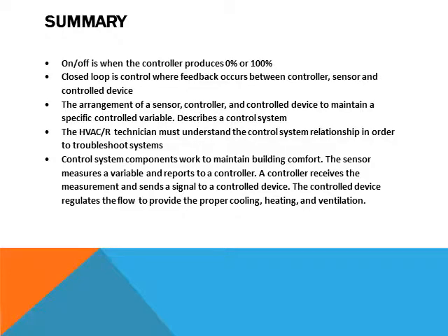Control system components work to maintain building comfort. The sensor measures a variable and reports to a controller. A controller receives the measurement and sends a signal to a control device. The control device regulates the flow to provide the proper cooling, heating, and ventilation.